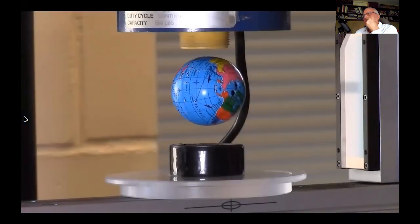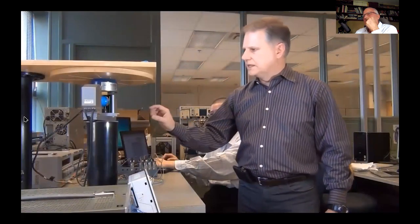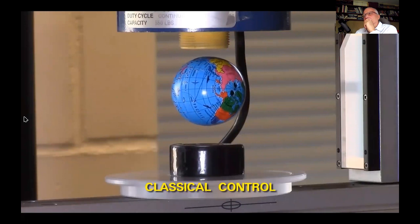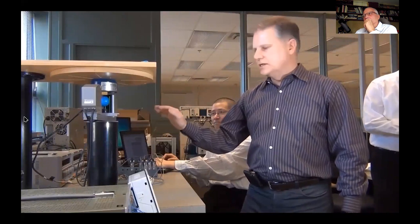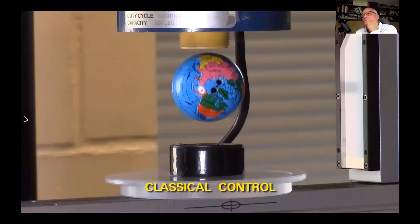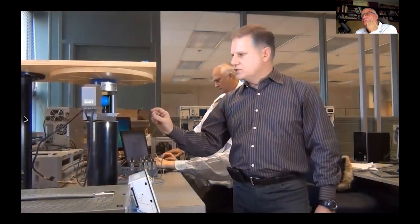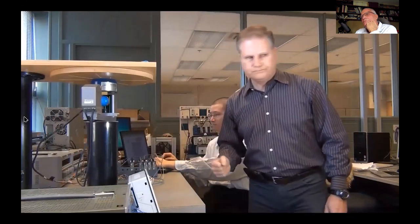So what we have here is the magnetic levitation device, and the ball is magnetically levitated right now, under the control of a PID controller, which is proportional integral derivative. What we see is that the ball is steady at a position, and then we change the set point so that the ball can move up a notch by about 1 millimeter, as we see here. The response time is not great, and there is a little bit of overshoot, which is something that we will correct with the new control.